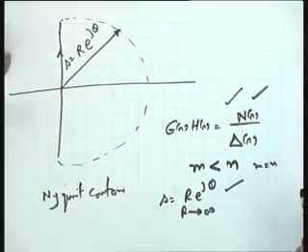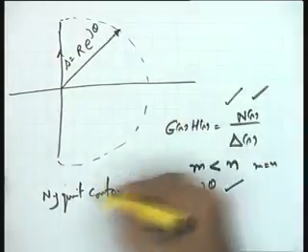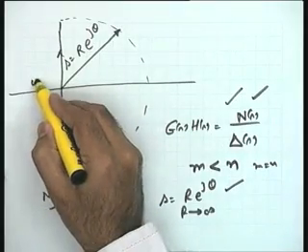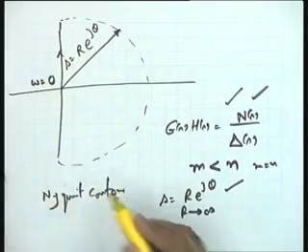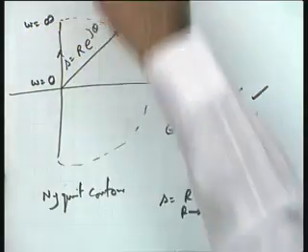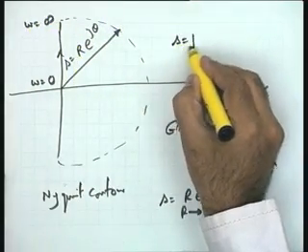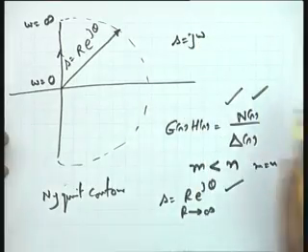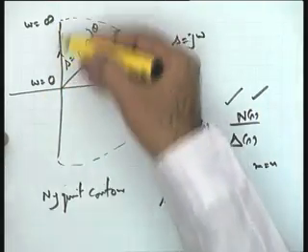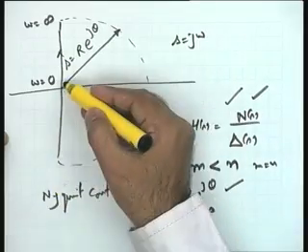So effectively, mapping of this total contour means starting from omega equal to 0, going to omega equal to infinity. On the imaginary axis, s is equal to j omega. So omega is equal to 0 to infinity, and the counterpart is minus infinity to 0.